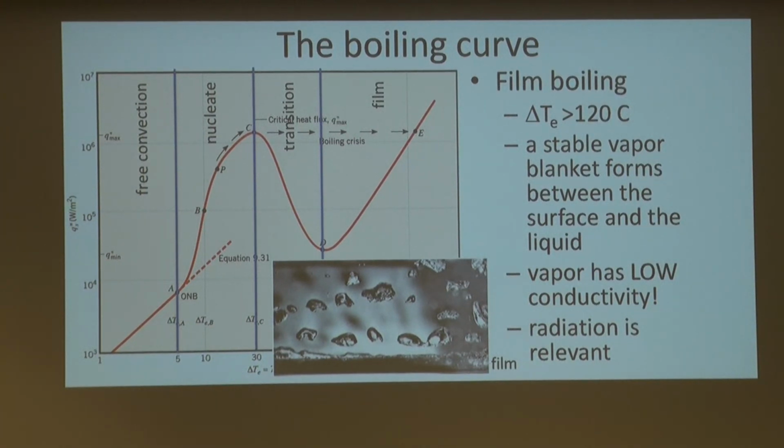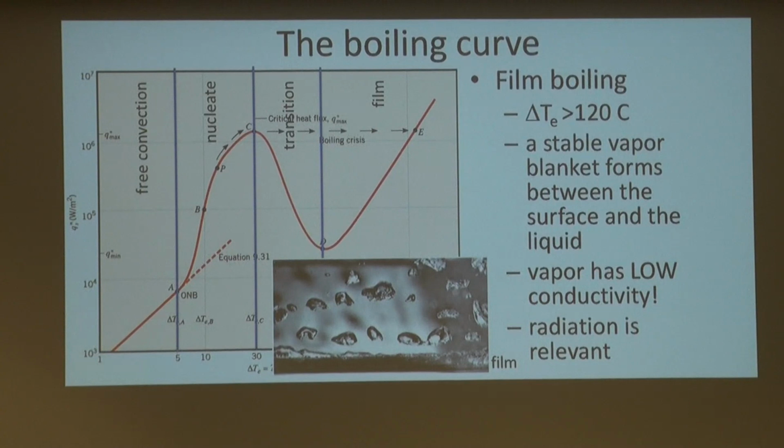Something interesting here is between the hot surface of the plate and the temperature of the fluid, we have the film, but in a gas, we can transmit radiation, right? So radiation happens to be important in here. If you were to calculate the heat exchange just based on the separation and the thermal conductivity of the gas, you actually should also account for the radiation between these two surfaces. Right? Very, very interesting. So let me show you this video.